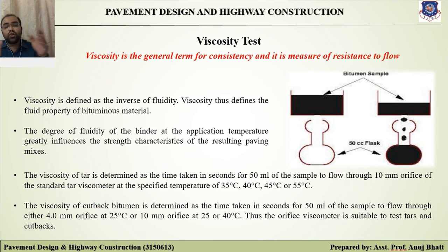If we talk about low viscosity, at low viscosity the bituminous binder simply lubricates the aggregate particles instead of providing a uniform film for binding action. In a similar way, high viscosity resists the compactive effort, and the resulting mix is heterogeneous in character, exhibiting low stability values.